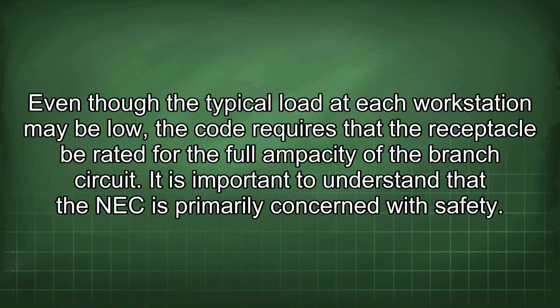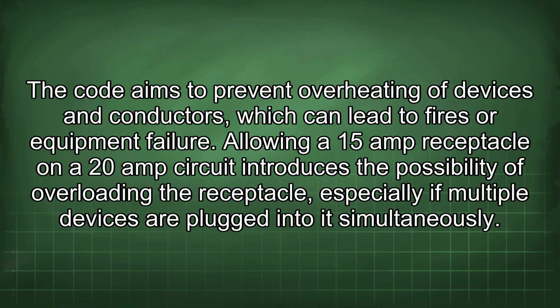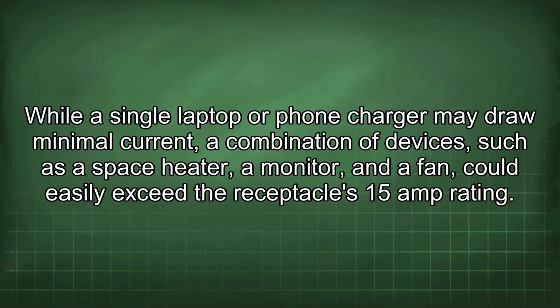It is important to understand that the NEC is primarily concerned with safety. The code aims to prevent overheating of devices and conductors, which can lead to fires or equipment failure. Allowing a 15 amp receptacle on a 20 amp circuit introduces the possibility of overloading the receptacle, especially if multiple devices are plugged into it simultaneously. While a single laptop or phone charger may draw minimal current, a combination of devices such as a space heater, a monitor, and a fan could easily exceed the receptacle's 15 amp rating.